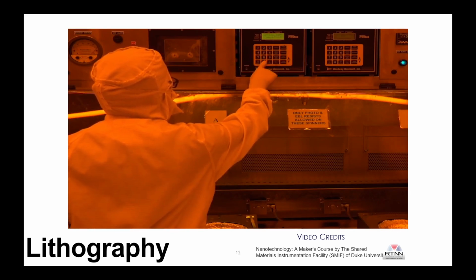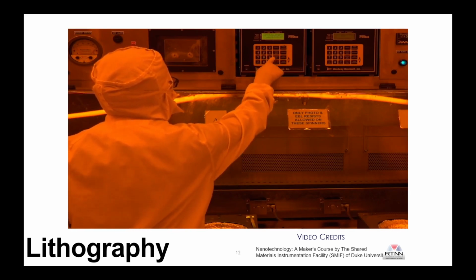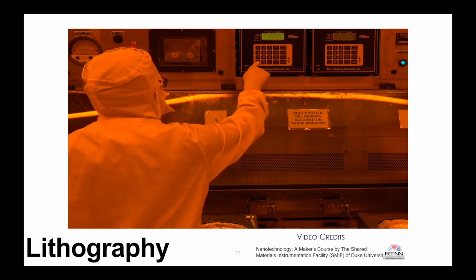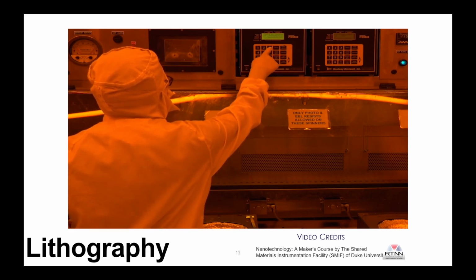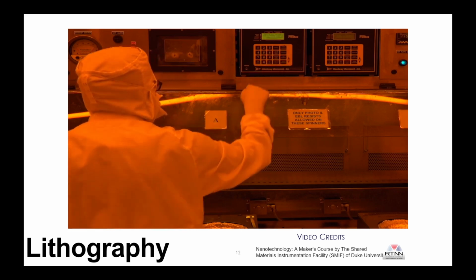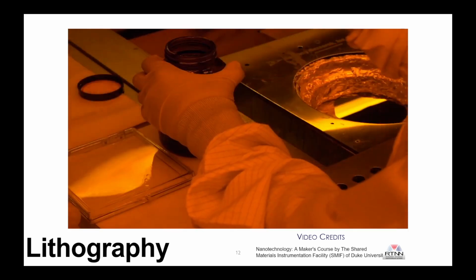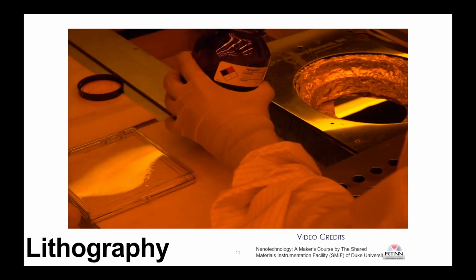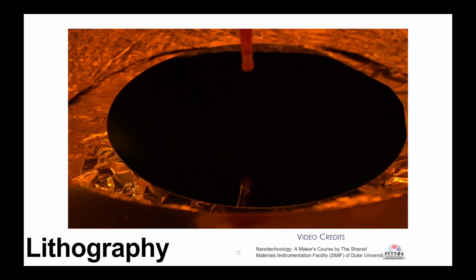This is the large scale production laboratory. The size of the wafer is very big, 6 inch, so you can fabricate many devices on a 6 inch wafer. This is the photoresist they are holding. Now they have to drop cast this photoresist.